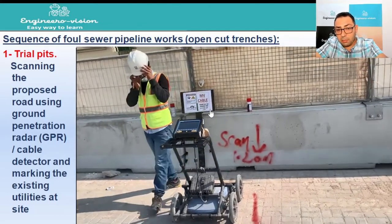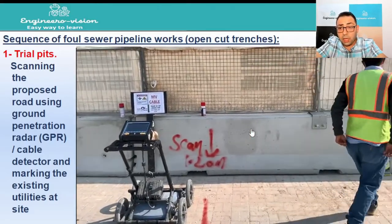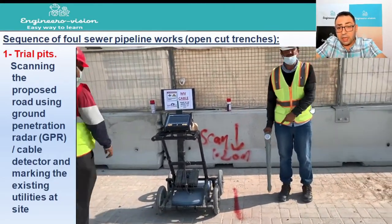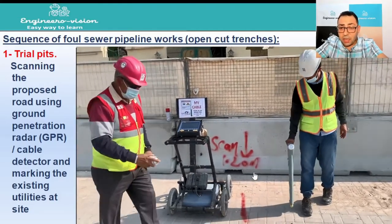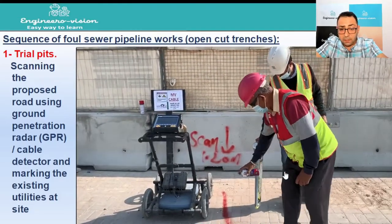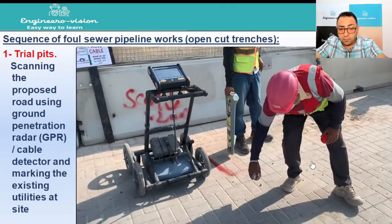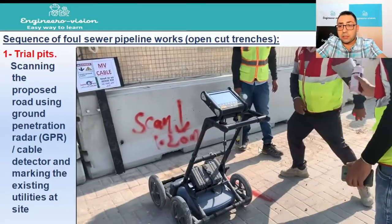And this is MV cable. He knows that there is MV cable here from the drawing, and based on that he determined this point and he started the scanning. And here he is confirming with the cable detector that there is an MV cable in this area. And this is the safety team marking on the ground the location of this utility.